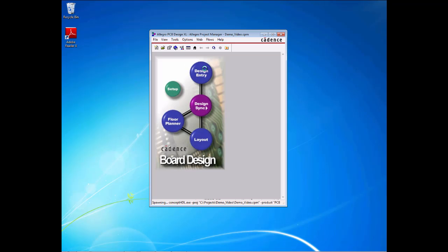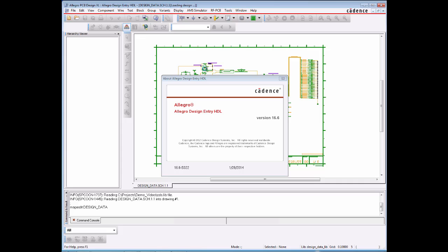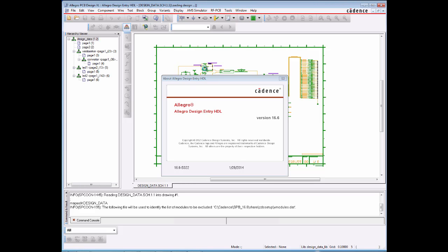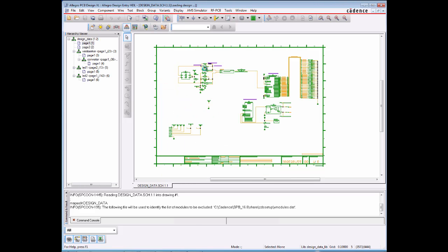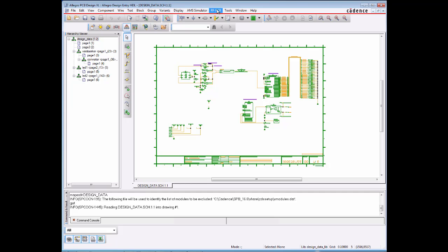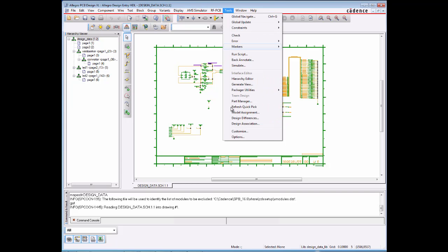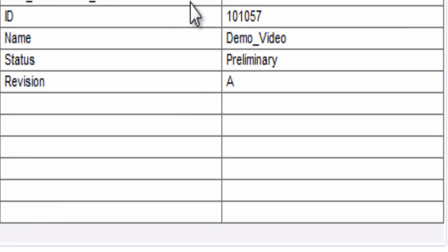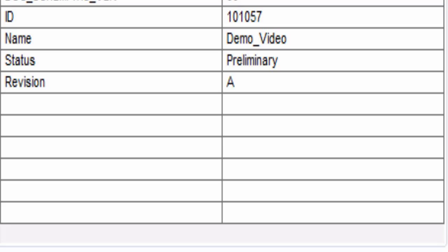After the design was assigned to an element in PLM, metadata were transferred from PLM into the design as well. In this case, that includes the identification number of the design container, the PCB, and the different assembly variants. If the relevant placeholders were already integrated in the design template, that information will automatically be shown in the design drawing frame. If not, they could be placed now.